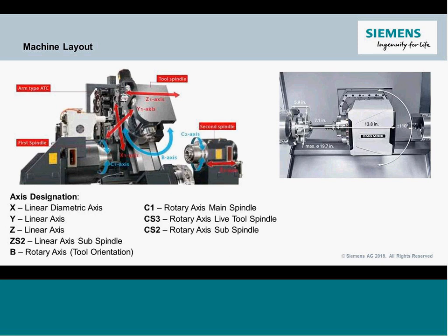The primary B0 location is at 9 o'clock, so the position that you see that head sitting in, which is the primary tool position facing the main spindle. And that's going to drive relative to that offset. So if I want to tell the tool to swing down from 9 o'clock to 6 o'clock, I'm actually going to give it a B90 positive value. And she's going to rotate counterclockwise down to that position. If I want to get to the sub-spindle, I give it 180.